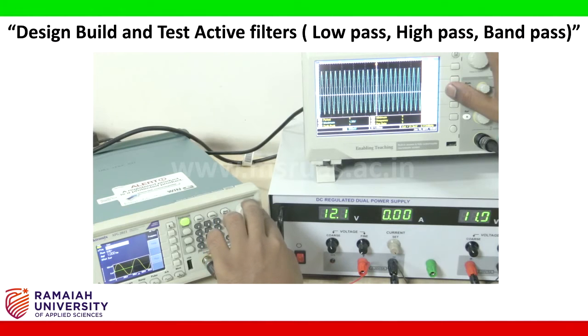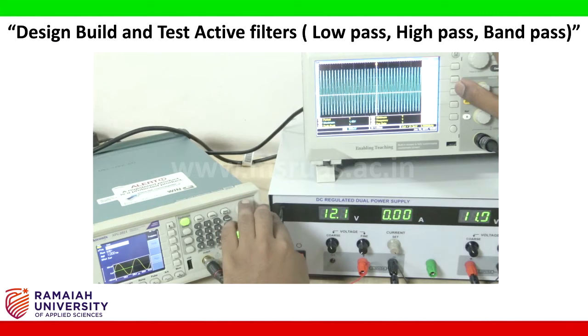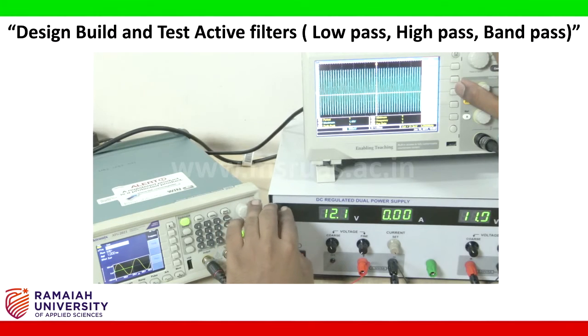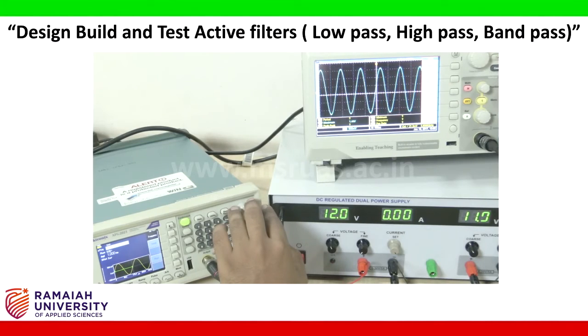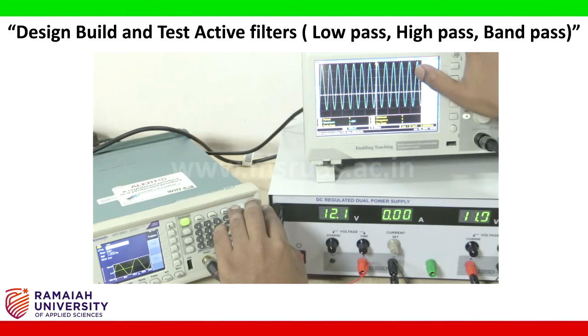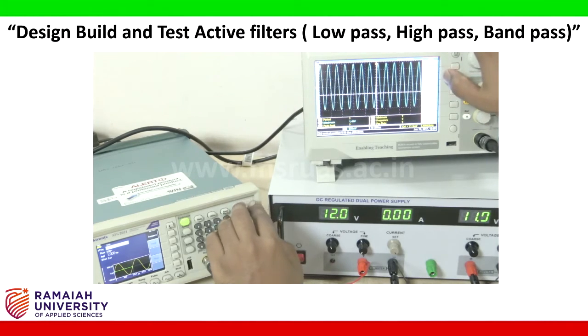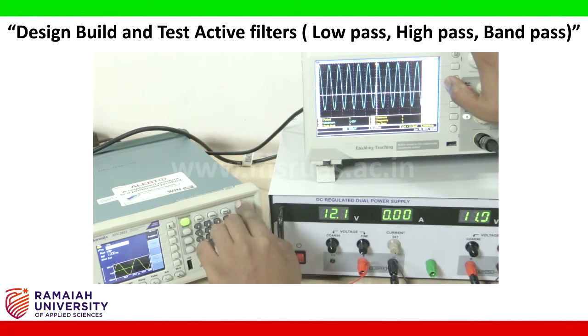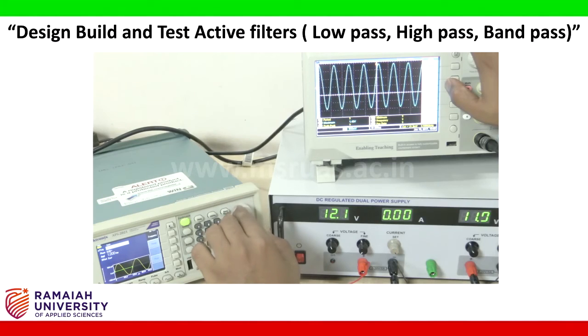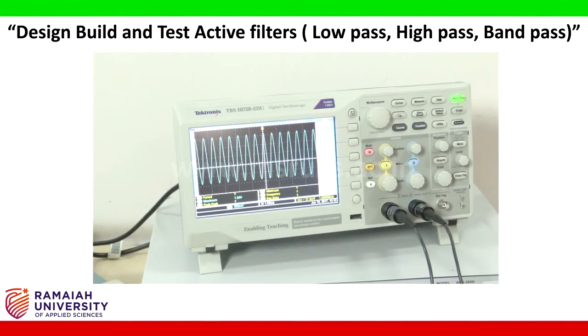So later on it will start to give a constant value. So at the output terminal, this is the constant we are expecting. Now it starts to increase to some other voltages. Now it will be raised to 6 volt peak to peak after 5.8. So we don't go to that much of design. We are using only for a 1 kilohertz frequency circuit design. So in that, the critical frequency of this high pass filter is 1.5 kilohertz.